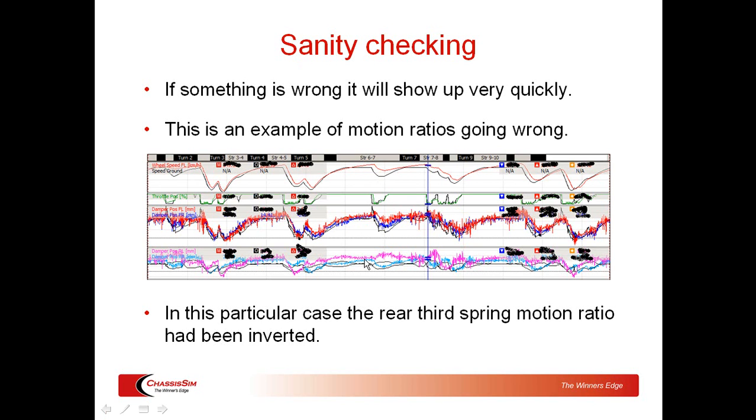The rear dampers are significantly lower than the front dampers, and this was actually from one of my sports car clients who gave me a call and said, "Danny, the Aero modeling isn't working, what are we going to do?" I instantly started to do the numbers, and when they were going at CLA numbers like 25, I figured, okay, something is seriously wrong here. I thought, hang on, something just isn't making sense. And they were running a very, very aggressive rear third spring. So when I inverted the motion ratio, all of a sudden, the correlation tidied itself up.